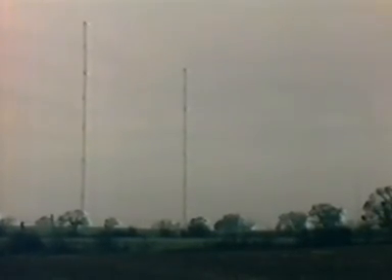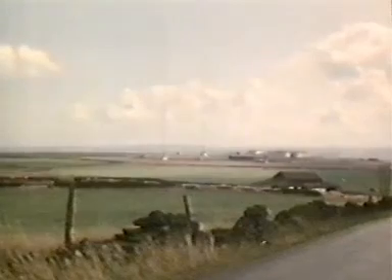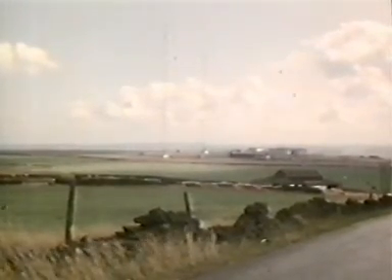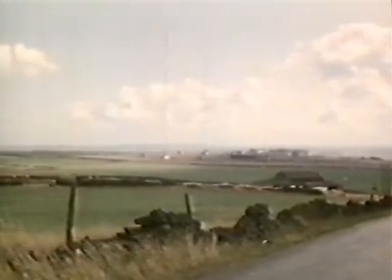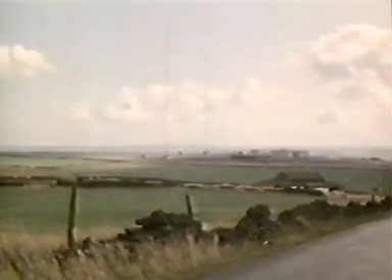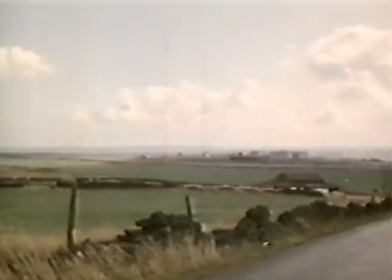To transmit long-wave radio, you need a long aerial. All these lines are just one wire, carefully strung and supported. It's so long because the radio waves transmitted have a wavelength of 1,500 meters. So a medium-wave aerial doesn't need to be as long. Sometimes medium-wave aerials don't need a special mast to hold them up.